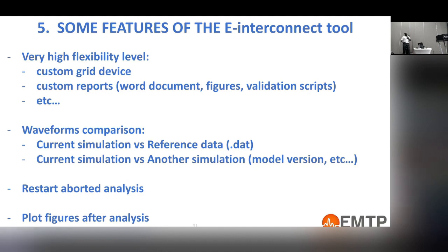Also, as I said, when the interconnect tool runs, it takes time. It may take more than 1 hour because it generates a lot of ECF files. And during the process, maybe something may happen. Maybe your computer may crash, or maybe your computer may run out of power. Imagine you are running 100 simulations and at simulation 25, something happens. In the tool, when you restart, the tool is able to know that it can restart your aborted analysis. It knows that previously it stopped at simulation number 25, and it will simply continue from there. So everything that has been simulated is not lost if something happens to your computer.